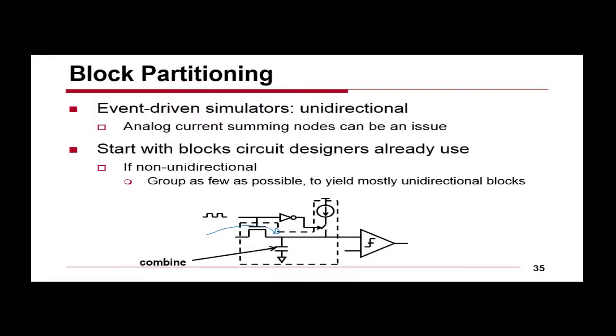So if you have a circuit that looks like this, where you have a sampler, so this was an ADC where we sampled a voltage on a capacitor, and then we ramped the voltage on the capacitor to measure how long this was, a voltage to time converter. Right? So we create a time delay which is proportional to the voltage. This whole circuit has to be in one analog model because I have to have all that coupling in my model. I can't break the current outside.